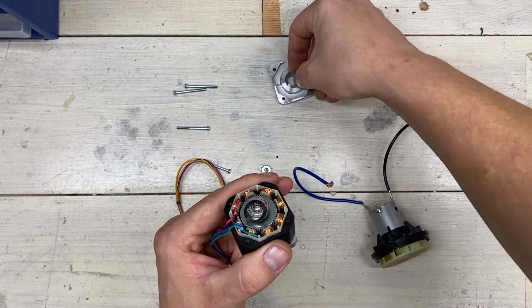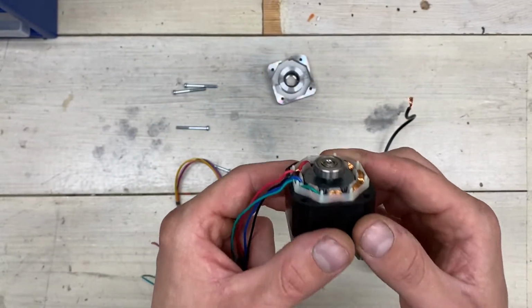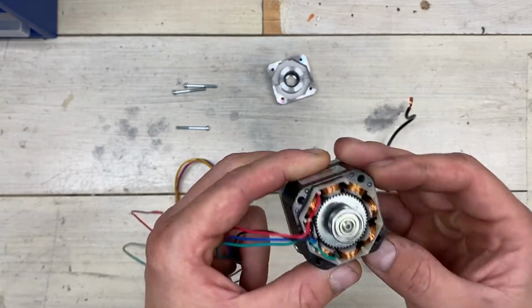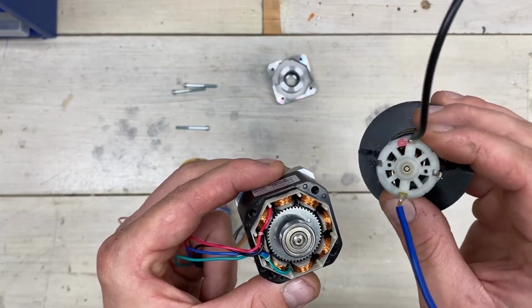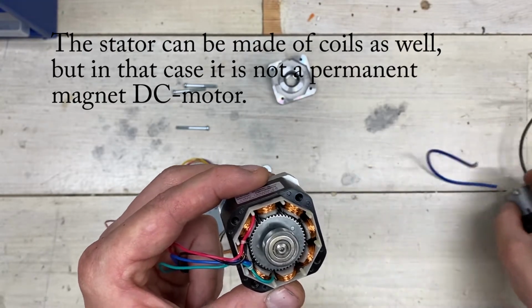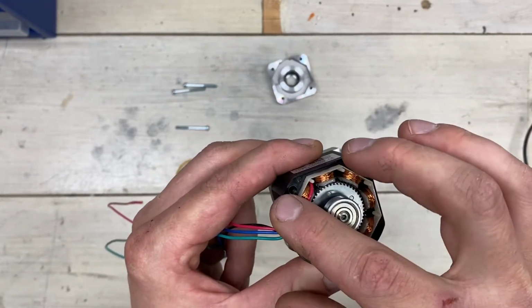And don't worry, I can get it back together again. And here you can see the first difference between a DC motor and a stepper or BLDC motor. As I showed you on this one, the coils or windings are on the rotor, the part that rotates. On a stepper motor or BLDC motor, the coils are generally on the outside, on the stator.